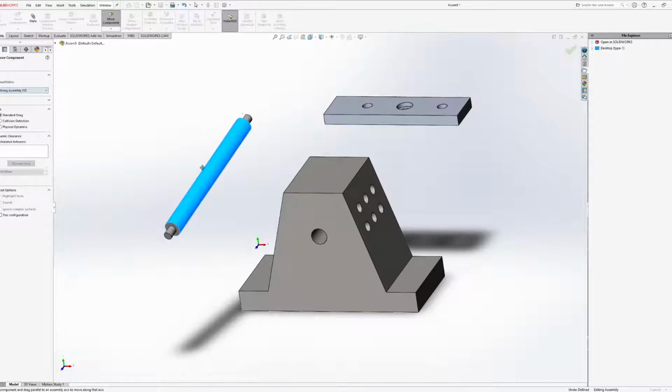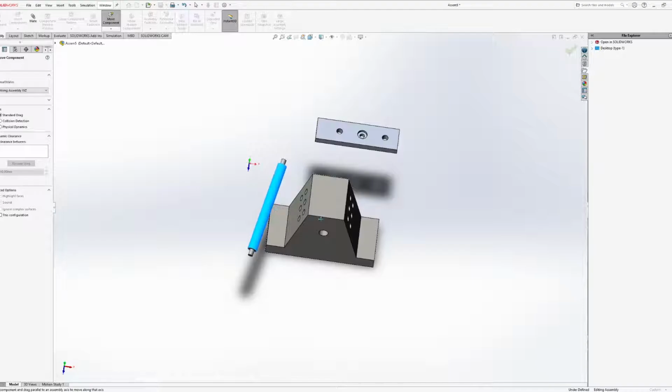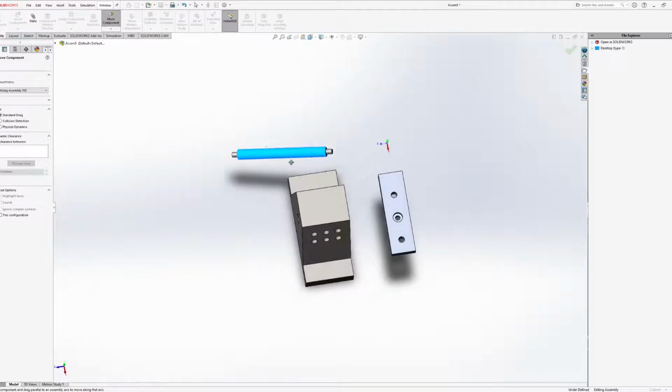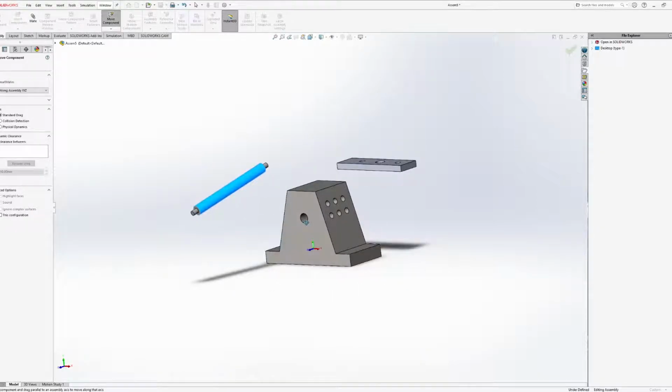We have along the assembly's global coordinates, so you need to be a little bit specific about this, but what's nice is that once you get it moving in one of your cardinal directions, it will only move in that direction. So you saw me moving it in the X direction. If I turn my interface a little bit more such that I want it to move in the Z direction, it moves quite nicely. I can do the exact same thing with the Y direction as well.